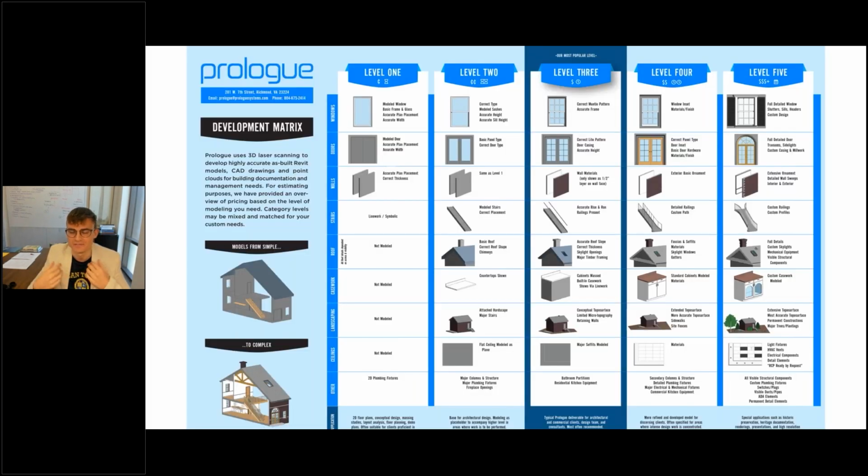Clients will send you a level of detail spec they adopted from who knows where, because they just don't know much about the process, and so they don't know enough to make their own spec. They assume since someone else got LOD 300 that they might as well get that too. Ask them why they need LOD 300. What questions will they be answering using the model? Walk them through the facility, element by element, system by system, and determine where they need detail and where they do not, where they need accuracy and where they do not.